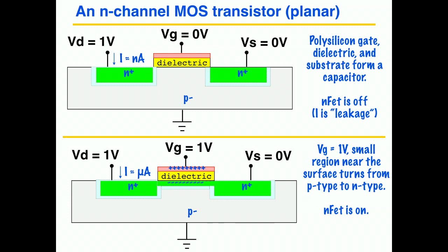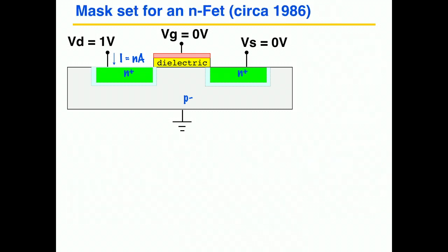But for now, you can just understand that if you put a high voltage on this gate of this NMOS transistor, then it effectively turns it on, and then we can get a current that will flow from here, if this is connected to a positive voltage, down to that lower voltage there. Okay, so that's the basic operation. They're pretty simple devices as far as semiconductor devices are concerned.